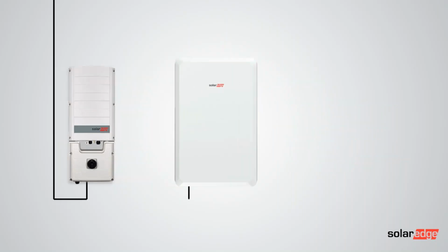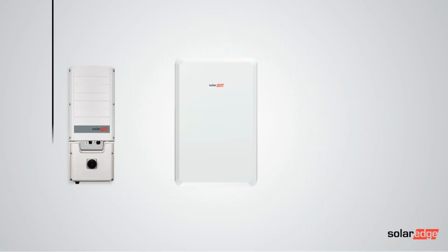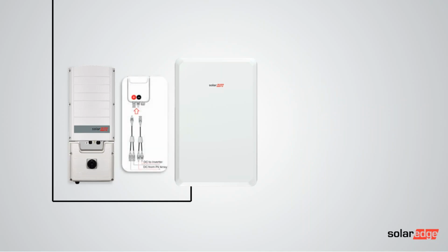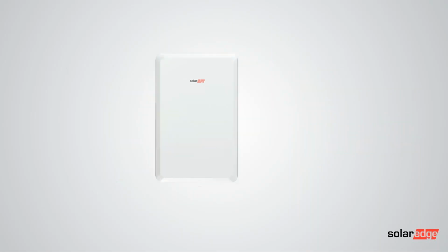Now, there's a couple of different options on how you can do the wiring, really around the fact that this could be an add-on or a battery being added to an existing installation. If so, then you've already got the DC coming down from the roof to the inverter. So you'll need to join the DC to that DC because the three-phase Resi inverter's only got a single DC input. So you need to bring them two together in the DCD. Alternatively, if it's a new install, what you can do is bring the DC straight to the battery and then use one of our branch connectors and then use the single input into the battery. A nicer, simpler way to do it. I mean, you could do this with an existing install if the DC cable allows.